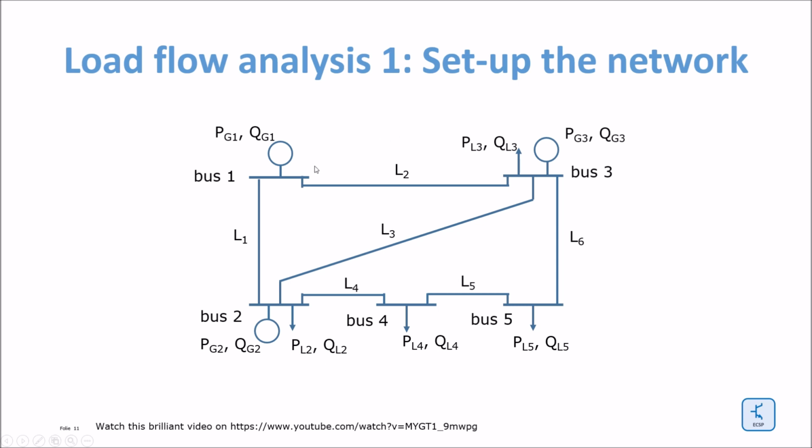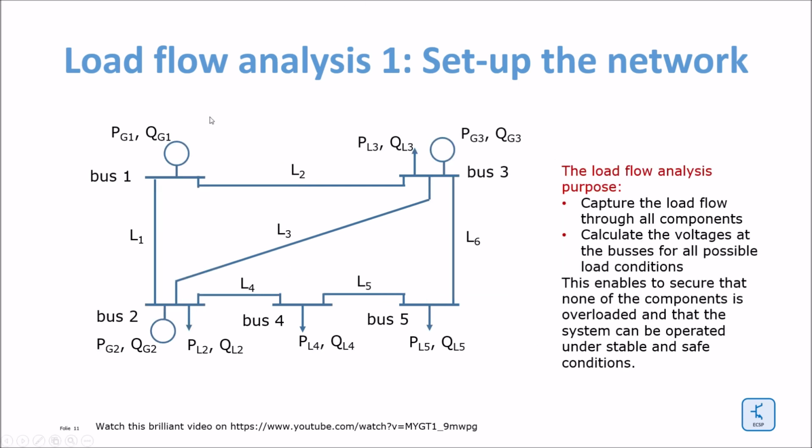I told you already that the buses stand for substations. In the first step, we assume now that we know all the power sources at all the buses, and we know all the loads at the buses. And knowing that, we want to capture now the load flow through all the components, in this case primarily lines.